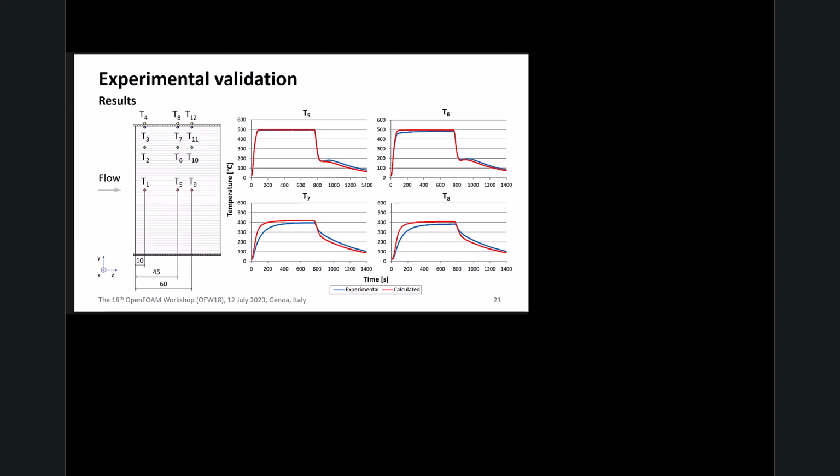As it's possible to see, the overall agreement is really good. We need to consider that in the simulation we don't model the thermal inertia effect of the thermocouples, which is visible in particular at the external point of the substrate and over the external surface of the canning. It is visible particularly during the heating phase and also during the cooling phase, introducing a time delay.